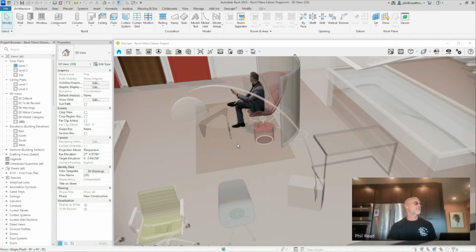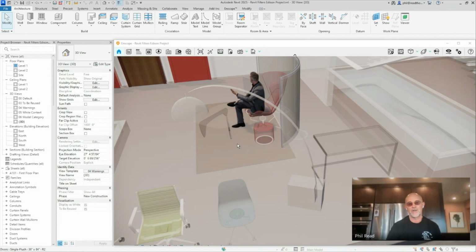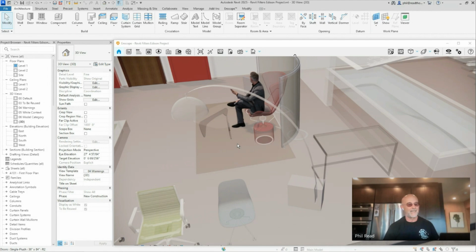That's just a Revit thing. You can override with a solid color or a pattern, but you can't override with a material, so you can't give certain things something like a warning tape. And you can't set that filter to be a diagonal hatch either. No, not in Revit.